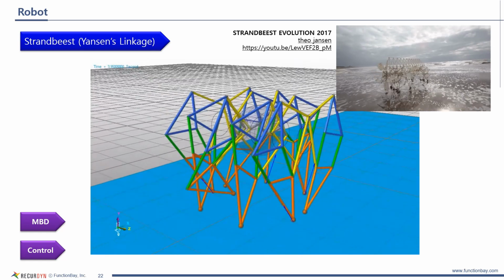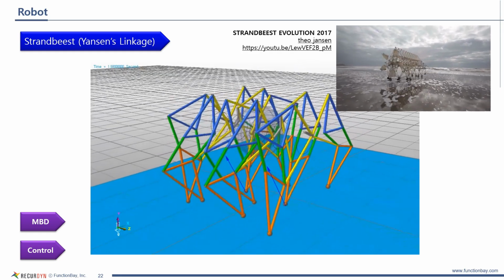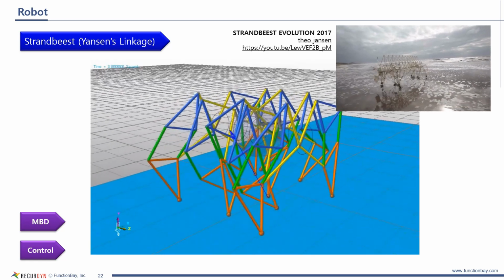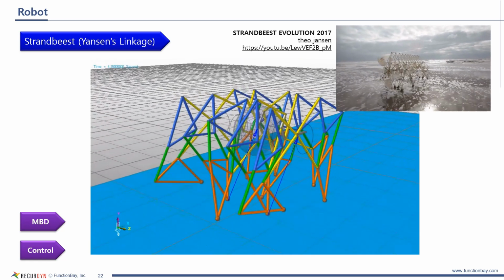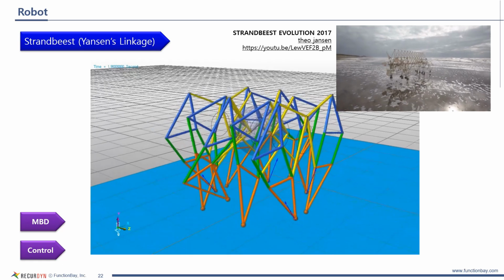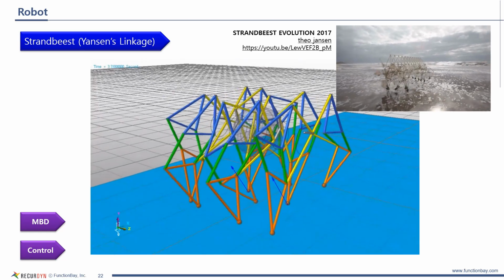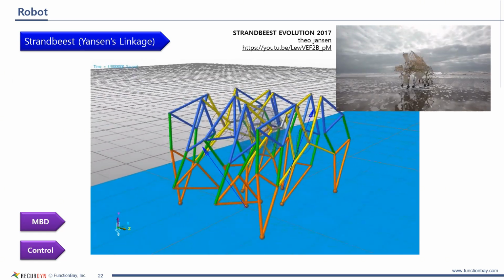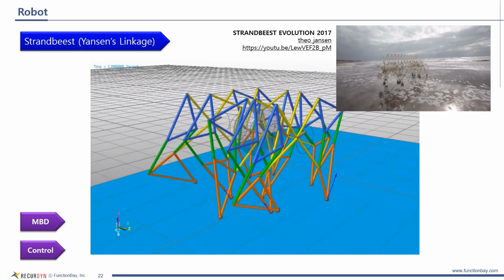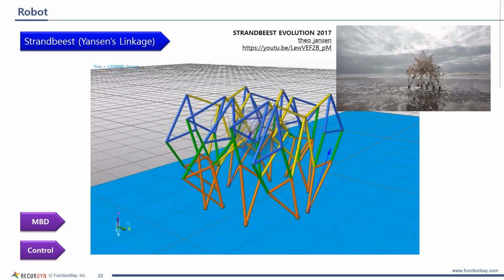What you are watching is a model of a Strandbeest using Jansen linkage. This is a walking robot model that employs a 6-bar linkage to create a very smooth walking motion. Although it is possible to mathematically calculate the shape, angles, and length of links, here it has been implemented through dynamic analysis. In this way, a dynamic analysis model that implements a robot system with a mechanical mechanism on a computer allows you to evaluate the dynamic performance of a robot without creating an actual model.